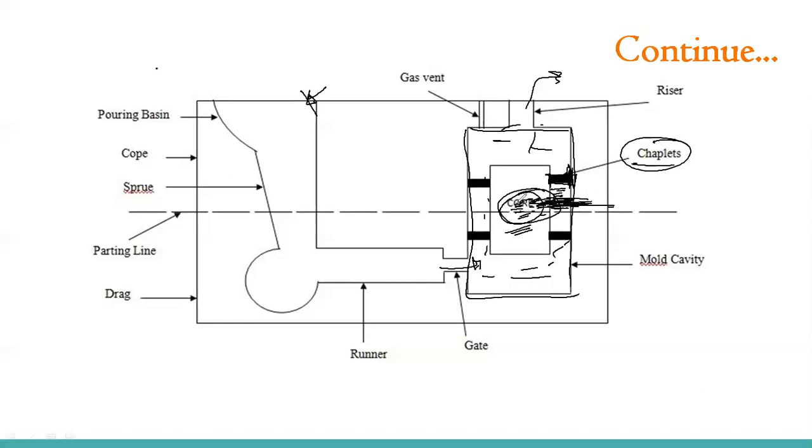Okay, now this is about the core, so that whatever sand particles are there can be removed through this area. And once the sand is removed from the side, we can easily weld this portion. So welding for the casting can be easily done, because it's a small area.